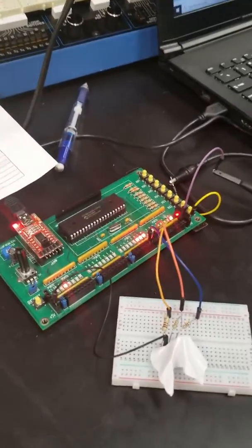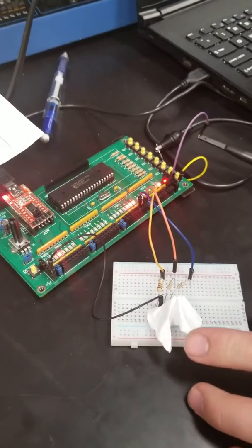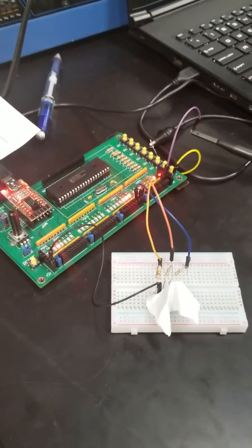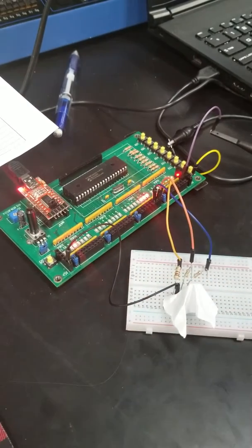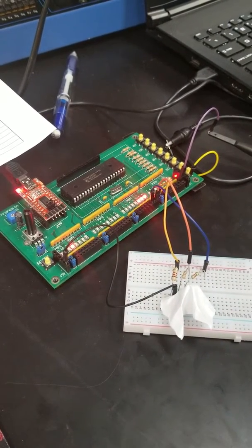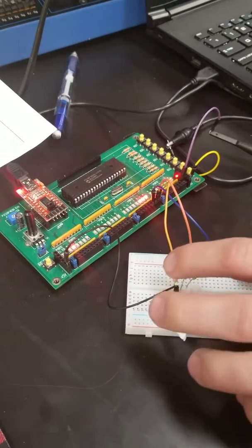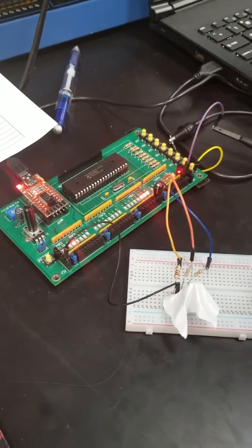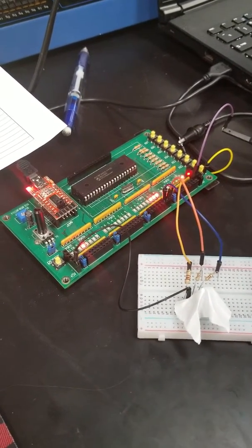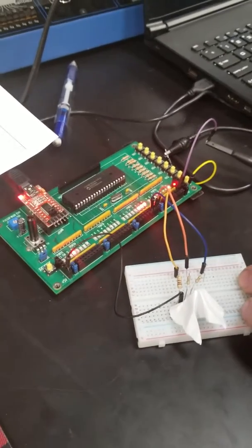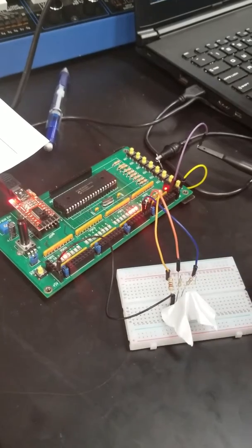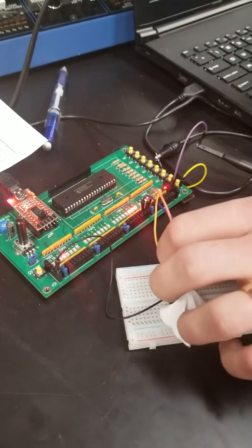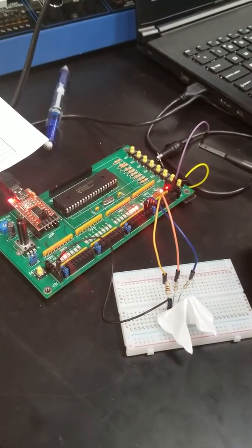Okay, so then here we've got the hardware. Underneath this little lamp of paper, we've got the RGB LED, and then it has a common 5 volts over here that's connected to all the little LEDs in there. And this one, a little bit weirder one, is 120 ohms, goes to the red just because it has a little bit lower voltage drop than the other two, which we've got connected to 82 ohms here. And then they all go into pins on the microcontroller.